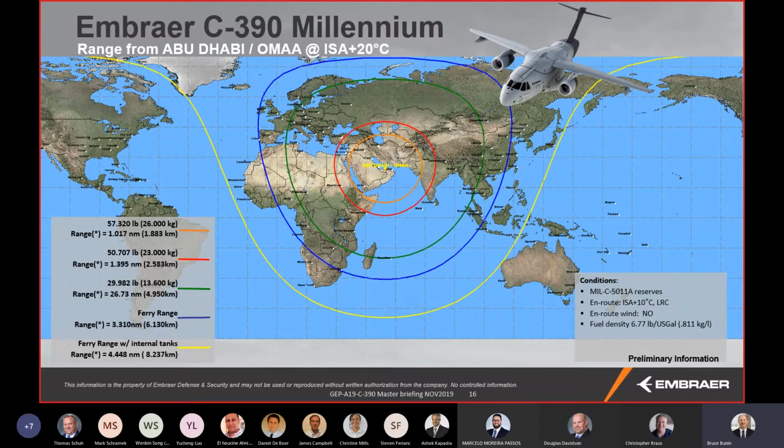I don't have a slide on it in this presentation, but the airplane has been designed to integrate 3 palletized fuel tanks that are anchored down in the cargo compartment and can connect to the fuel system in the upper part of the fuselage. And the pilots can actually use those tanks as they would, in any other wing tank. It's transparent to them.